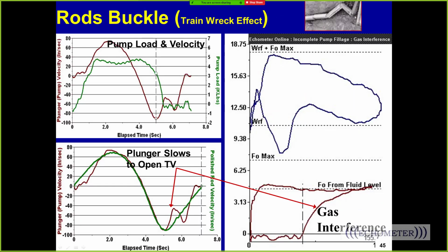If we were to look at this data for this well right here, and this were collected with a polished rod transducer, we look for where the pump fillage line is, and the software is supposed to identify where the traveling valve opens, and then we look to the left and try to find the maximum velocity point right there after the valve is open. That's the maximum downward velocity line, and that becomes the zero offset.